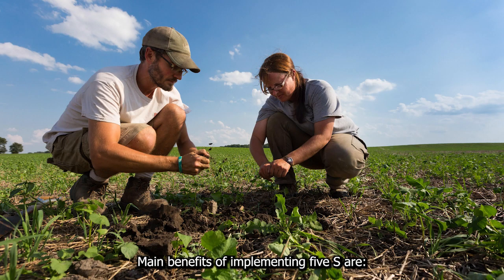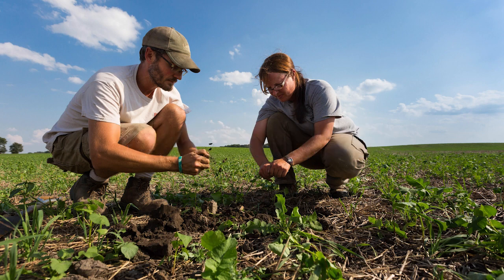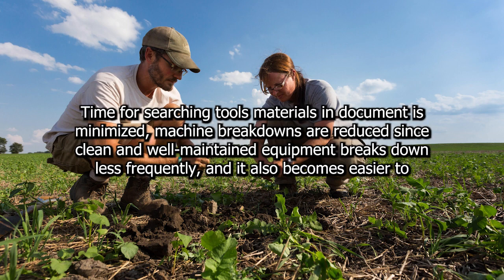Main benefits of implementing 5S are: the workplace becomes cleaner, safer, well-organized and more pleasant. Floor space utilization is improved. Workflow becomes smoother and more systematic, and non-value-added activities are reduced. Time for searching tools, materials and documents is minimized. Machine breakdowns are reduced since clean and well-maintained equipment breaks down less frequently, and it also becomes easier to diagnose and repair before breakdowns occur, therefore extending equipment life.